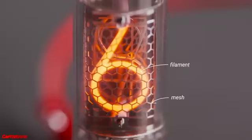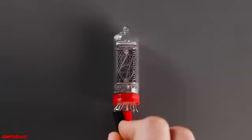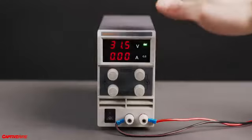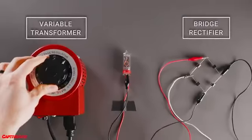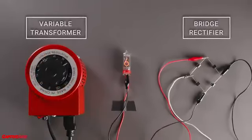So to make these work, we just have to apply voltage from the mesh to one of the digit filaments. Each one has a different pin at the bottom. Unfortunately, these take a lot of voltage, like 85 volts DC just to turn on. My DC power supply doesn't even go that high, so I use this variable transformer and the bridge rectifier we made in the last video to get higher voltage DC. If you haven't seen that video, I've attached the link in the description.